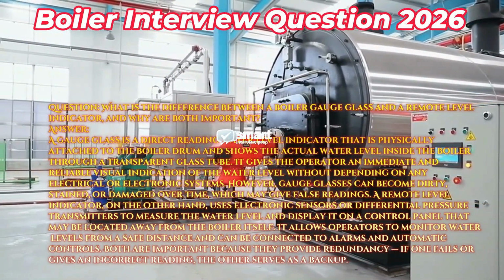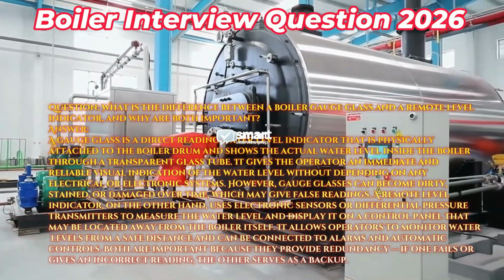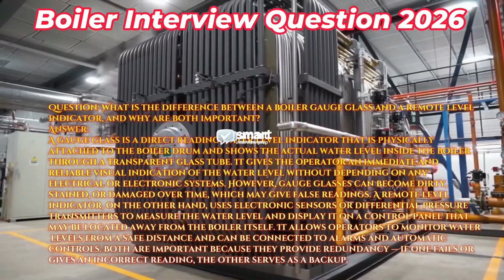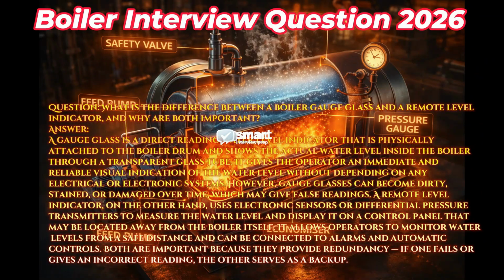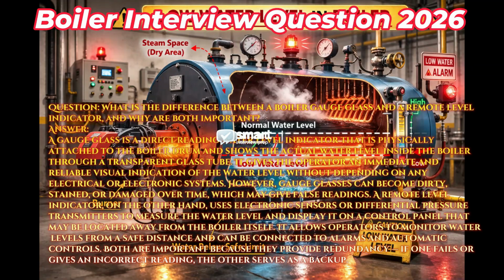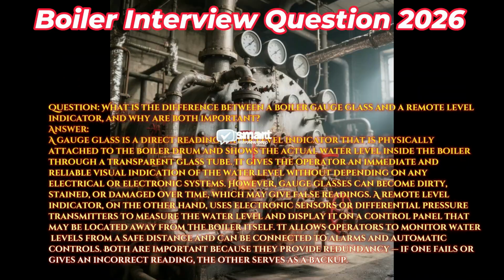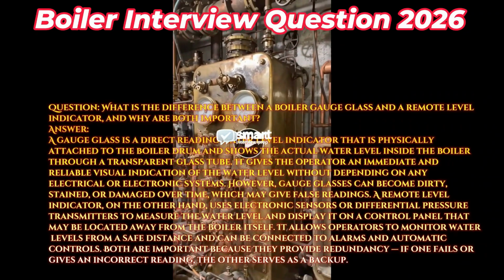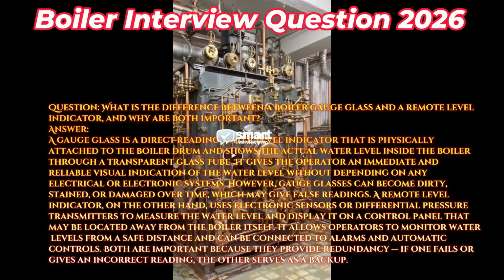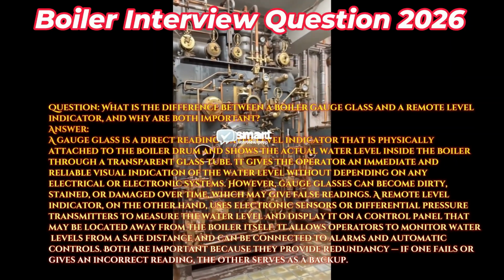It gives the operator an immediate and reliable visual indication of the water level without depending on any electrical or electronic systems. However, gauge glasses can become dirty, stained, or damaged over time, which may give false readings. A remote level indicator, on the other hand, uses electronic sensors or differential pressure transmitters to measure the water level and display it on a control panel that may be located away from the boiler itself. It allows operators to monitor water levels from a safe distance and can be connected to alarms and automatic controls.